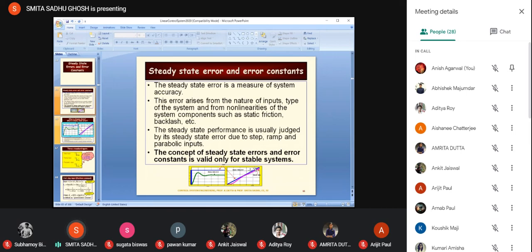Note one thing, that is basically in the figures that are shown on this page, I have used a step and a ramp. So in the case of the ramp, though the input is changing and hence the output is also going to be changing, nevertheless we do speak of steady state error. So what does a steady state error in that case imply? It implies that there is a constant difference. Say for example, if I have a constant steady state error of 0.5 units, what does that imply? It means that after the transients are over, if I have applied a ramp, the difference between the input and the output would be that 0.5 units, or whatever the steady state error is.